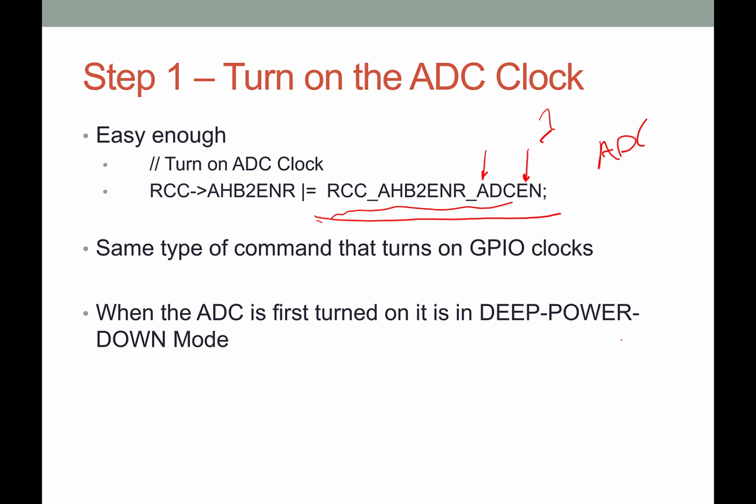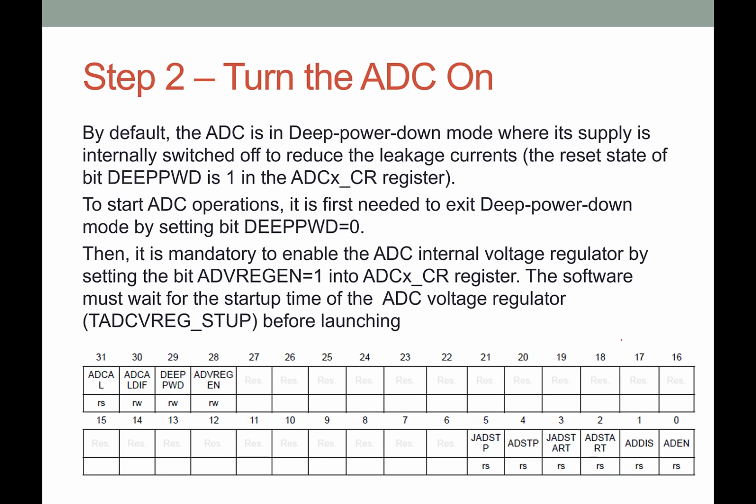Anyways, you have to take it out of that deep power mode, and you might ask why it is in that deep power mode in the first place. Well, it's there basically to save power. With these analog to digital converters, changing voltages and doing this comparison, you're running a part of the overall microcontroller that's pretty power intense compared to other things. So if you're not using it, you better turn it off so that you don't expend the power related to that.